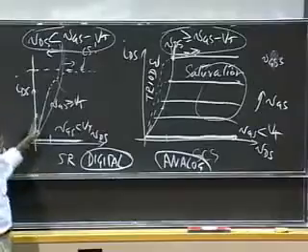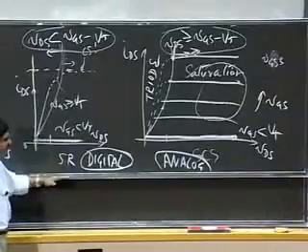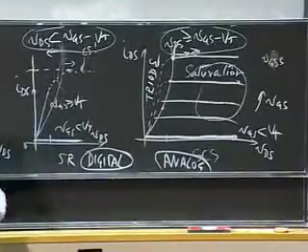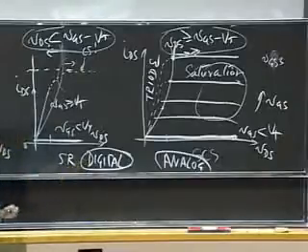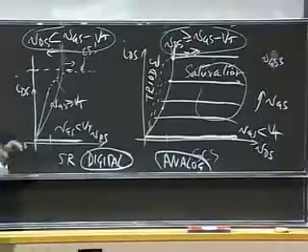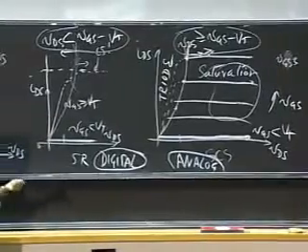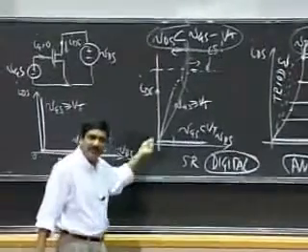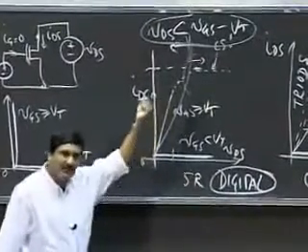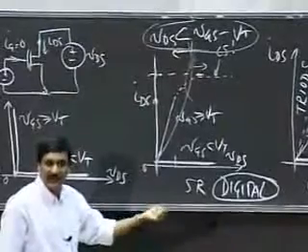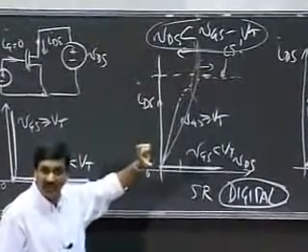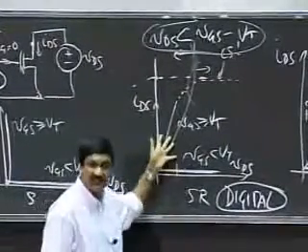And for digital designs, we'll simply use the SR model. It turns out that this is realistic because in the digital designs that you have seen and will be seeing in this course, when the pull-down MOSFET is on, the output voltage is pulled down close to ground. So VDS is very, very small. So it does make sense that this model applies.